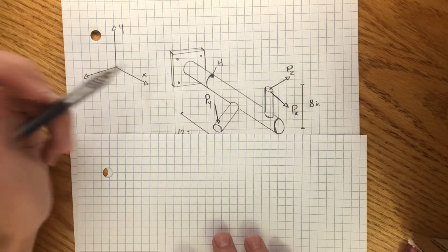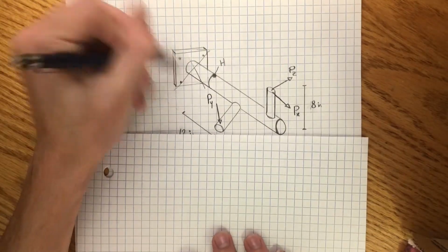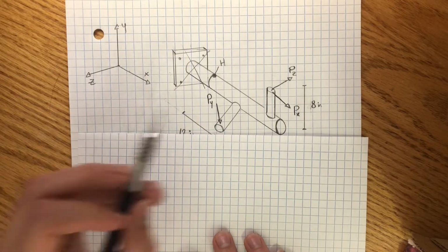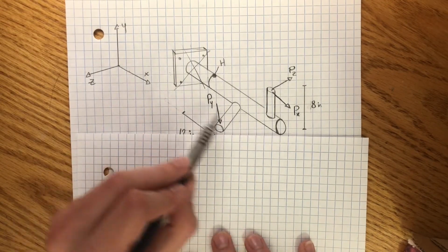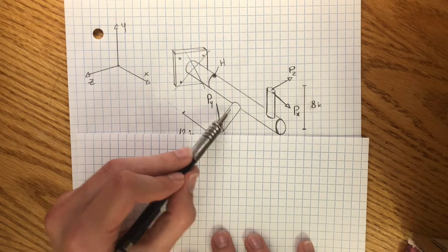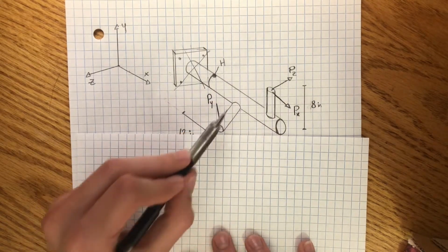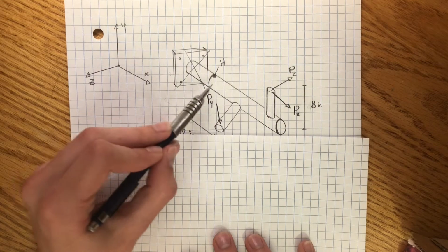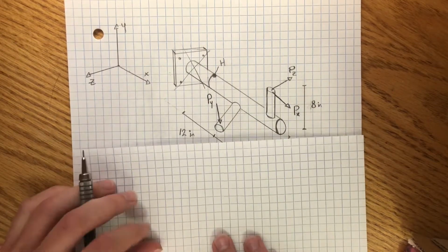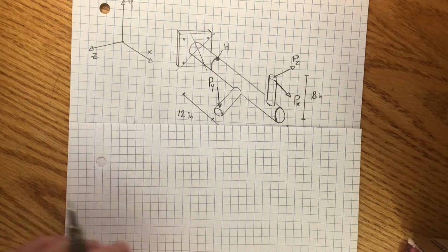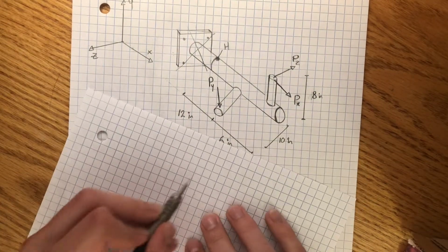So we're just going to chop this whole section off, and we're just going to work with this piece because we know that this isn't twisting or bending or moving. So whatever forces and moments are applied to this, there are reactions that are equal and opposite in this cross section right here.